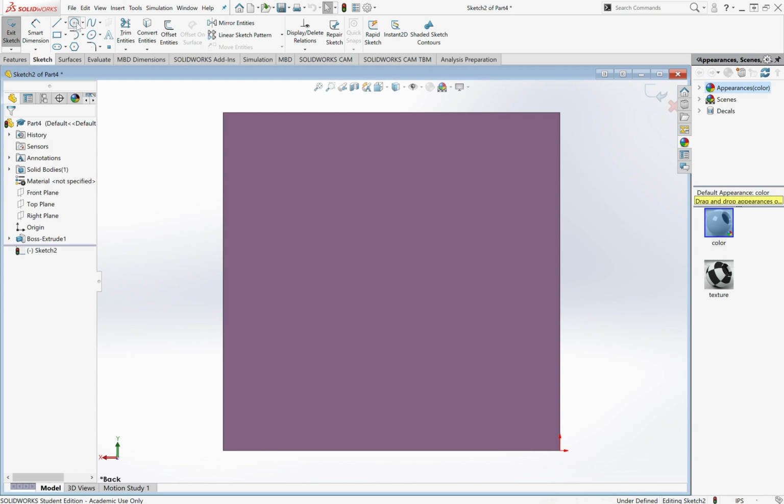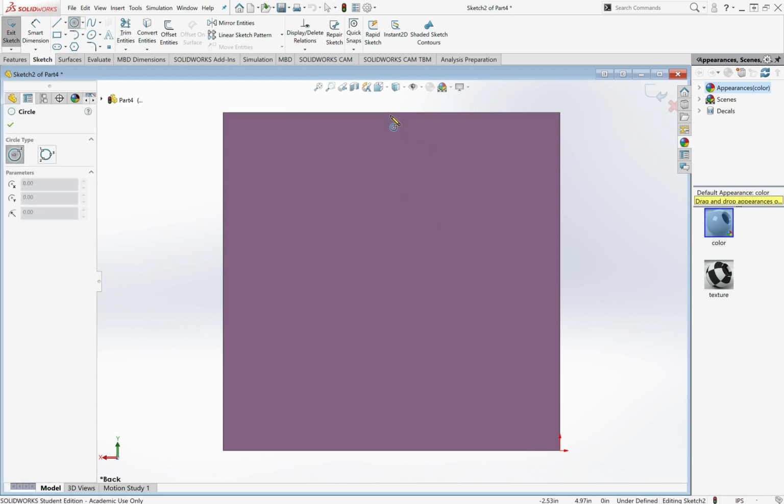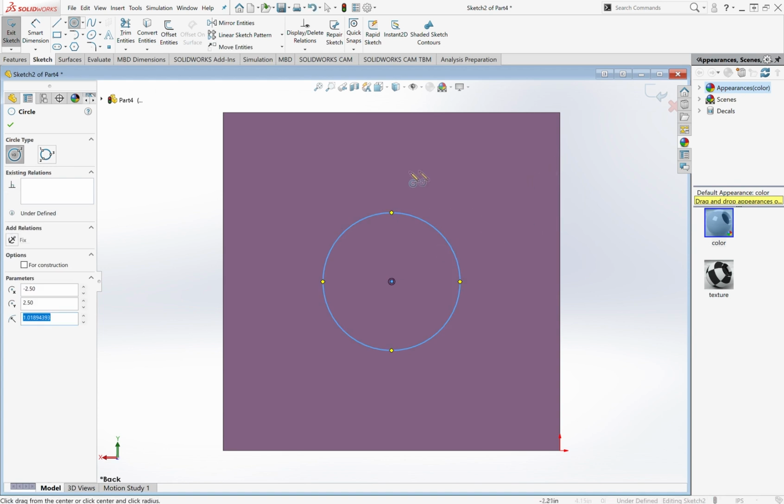Circle again. And then find that orange. And I'm going to go down. And you see this blue dashed line means I'm in line with that center of the edge. Perfect. Now I want to be centered on this edge too, because I want to be perfectly centered. So I'm going to find that. And eventually I can find where both centers are. I'm going to click, and now I'm going to draw my circle. And maybe you're kind of struggling keeping in line with that center point. I totally struggled with that. So let's do another way.